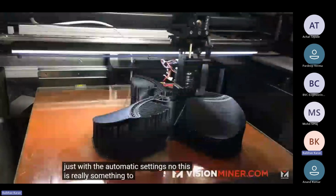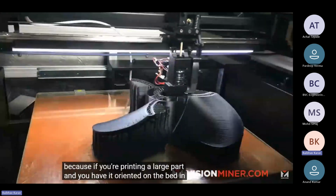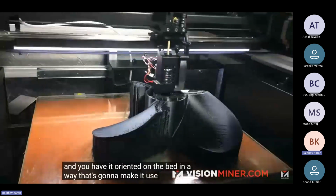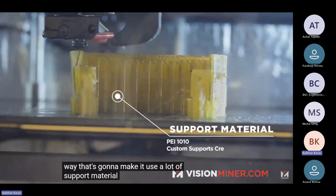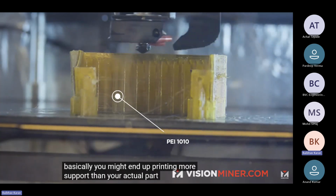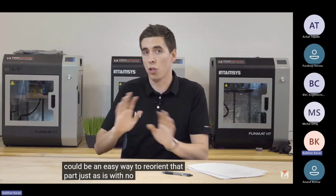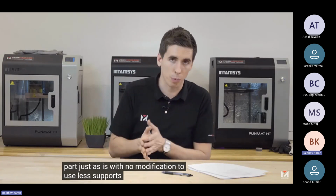Now, this is really something to take into account, because if you're printing a large part and you have it oriented on the bed in a way that's going to make it use a lot of support material, you might end up printing more support than your actual part. And there could be an easy way to reorient that part, just as is with no modification, to use less supports.